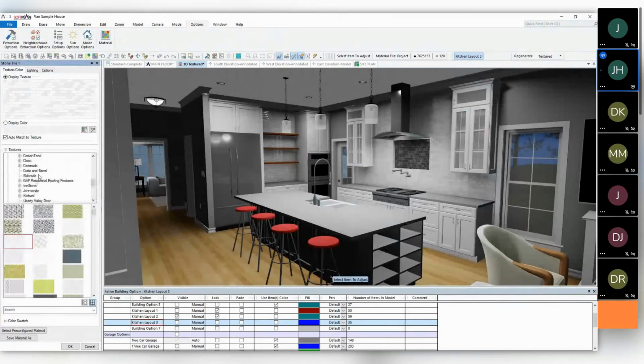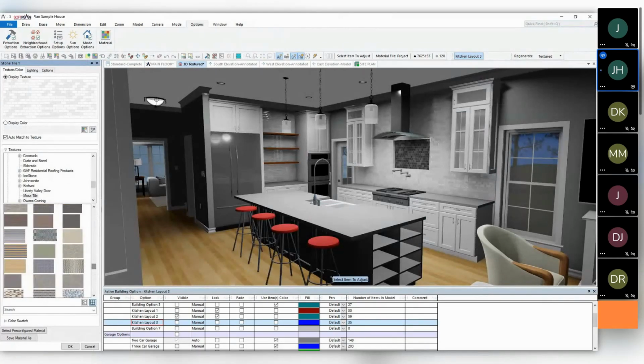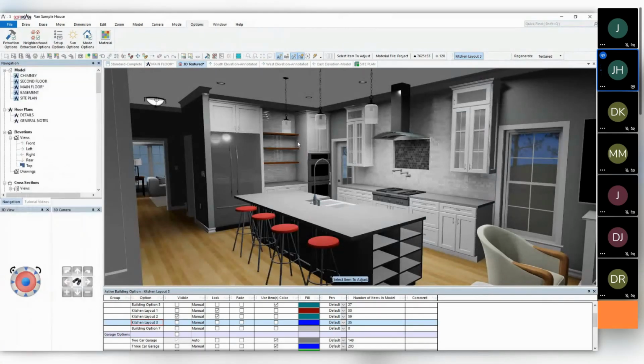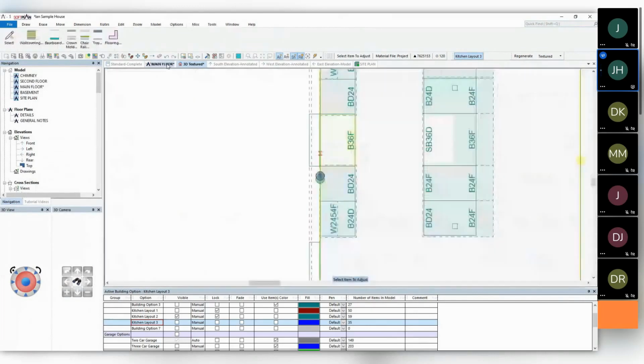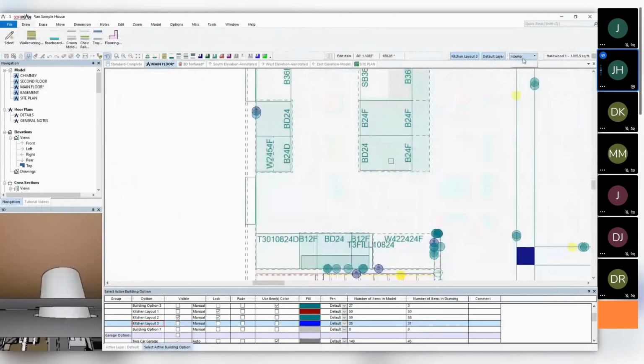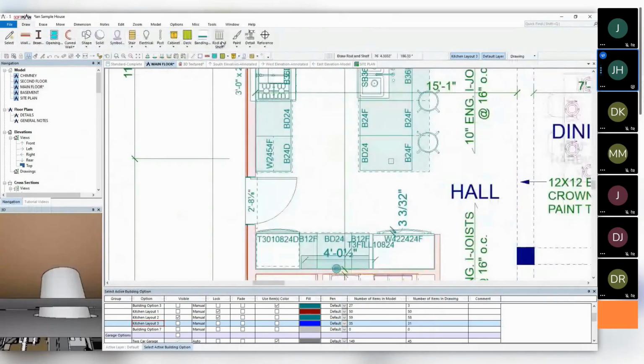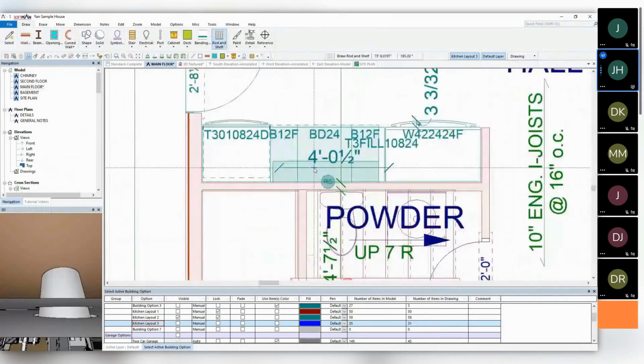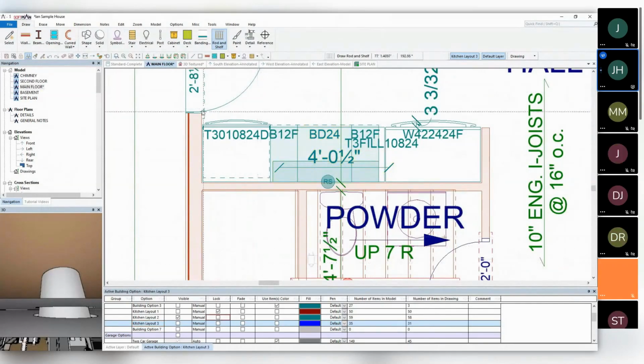And I went down into the Softplan plus Mosaic tile, and there are dozens and dozens of tile symbols to select from. So all of that can be added in there. The shelving that you see over here is just a rod and shelf. When I came in, inside drawing mode, and selected draw rod and shelf, I simply sketched it across, and then as I edit this rod and shelf, I'll be able to modify its depth to only 9 inches, and I turned the rod off. That's another option that you can do within the model as well.